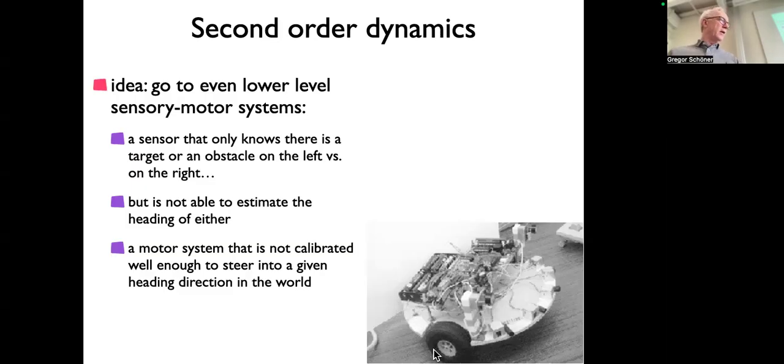So if they run on carpet, then they will run more slowly than if they run on hardboard or whatever mechanical condition. This is a demonstration that we don't need this form of calibration and all that, because the planner itself makes an attractor, and the dynamic system, the attractor, does the control. So if you don't turn it enough, well, then you get the sensor information that the obstacle hasn't been avoided, so you turn more. So without relying on a control system somewhere else.